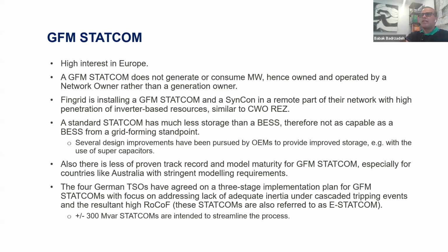So this obviously provides the particular advantage that it can be designed and operated by people that know the network best. As an example, I've put the recent work that Fingrid has been doing to install grid forming STATCOMs and a synchronous condenser in a remote part of the network. The specific objective here is to release hosting capacity of grid following inverters, wind farms in this case, that would not otherwise be able to operate stably under those conditions.